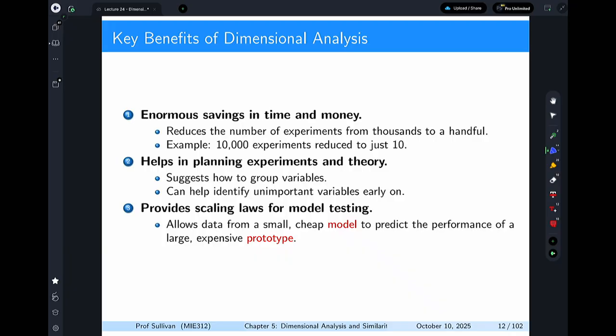And if you look at some of the literature out there, you'll see this is how people present it. If I'm going to publish this in a journal, they do not want to see values of force of 100 newtons, 2,000 newtons. They want to know what the drag coefficient is and the Reynolds numbers. That way, I can compare my work to other people in the world.